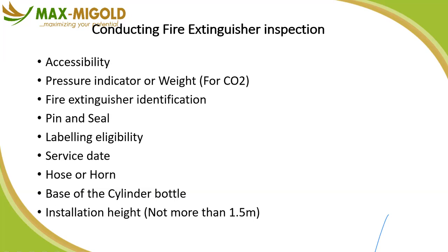So when I say change, not actually change in material. For instance, you've got maybe just one electrical panel in there, and you have a 5 kg CO2 extinguisher, which you think from the assessment is sufficient. Then suddenly you bring in additional panels. Most definitely, this single CO2 may not be adequate, may not be sufficient. Then you bring in additional, or you even change the size.